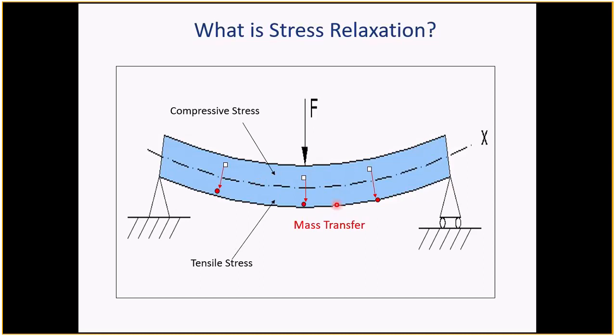Because if you take this load off after a time, this curvature would be frozen in, would be plastically retained. So stress relaxation is the conversion of an elastic stress into elastic strain into a plastic strain. And this transfer of elastic strain into plastic strain is enhanced by having point defects, by having an elevated concentration of point defects.